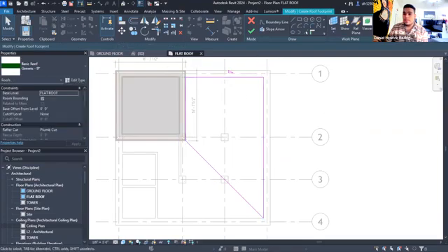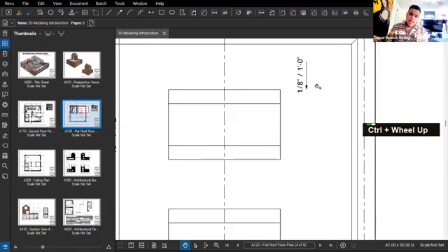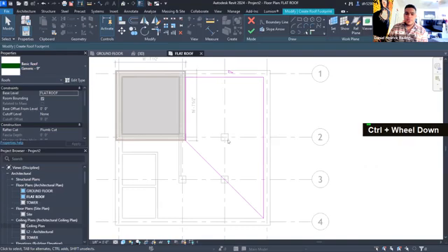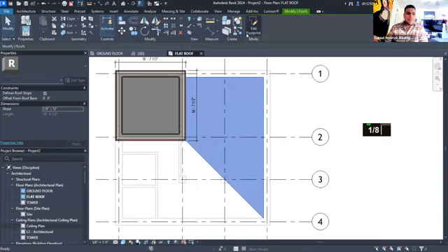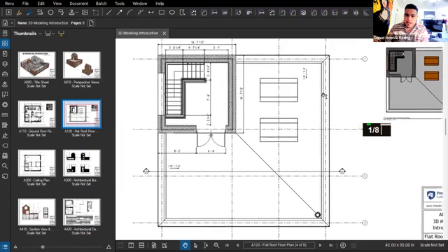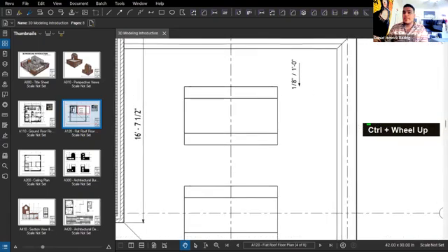And then the slope is also defined on the drawing here. It says 1/8 to a foot, so it's 1/8 to 12 inches. We're gonna go back to Revit, and where it says here 9 inches to 12 inches, we're gonna do 1/8 to 12 inches, and we're gonna hit apply. And that's our roof, okay. Let's take these again. Yep. So we got 1/8 to a foot, perfect.